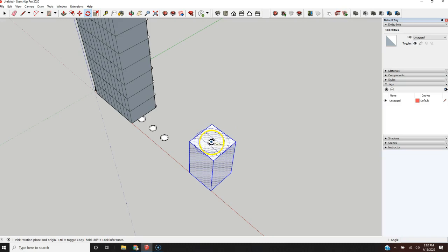There's the letter Q. I want to grab this in the middle, so let me draw a line from here to here. And now let me reselect Q, and what I can do is select the midpoint from here. So you have endpoints and midpoints. I know that if I was to grab this, you see how this line right here turned red? This is on the red axis. We'll get to that. And this is on the green axis. And this allows you to draft orthogonally.